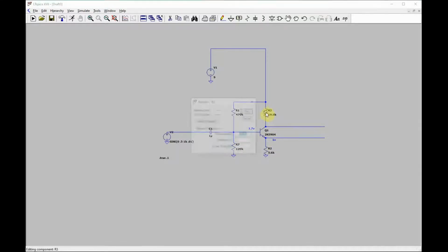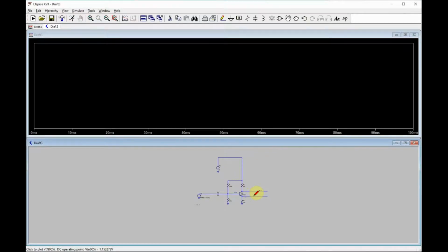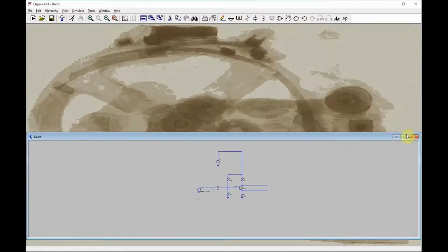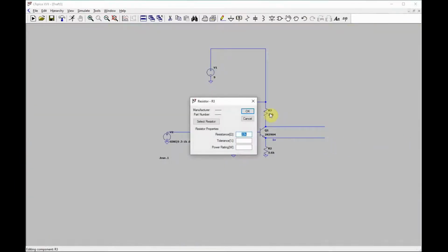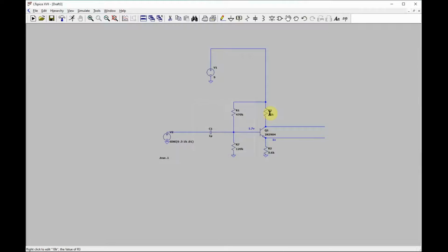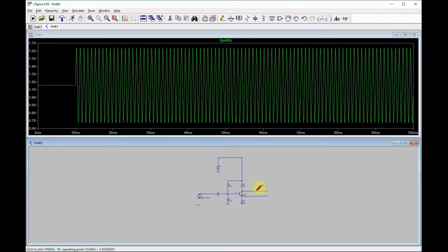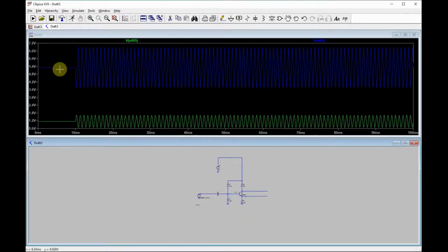So, if we do 22K, let's see what we got there, which is a real value. And it's being pushed down a little bit more to 4.5. You're going to lose headroom either way. I guess 18 is probably your closest value, and the gain is not going to be quite 3.5, but this puts it in a little better area. So that's how you get your 4 resistors.